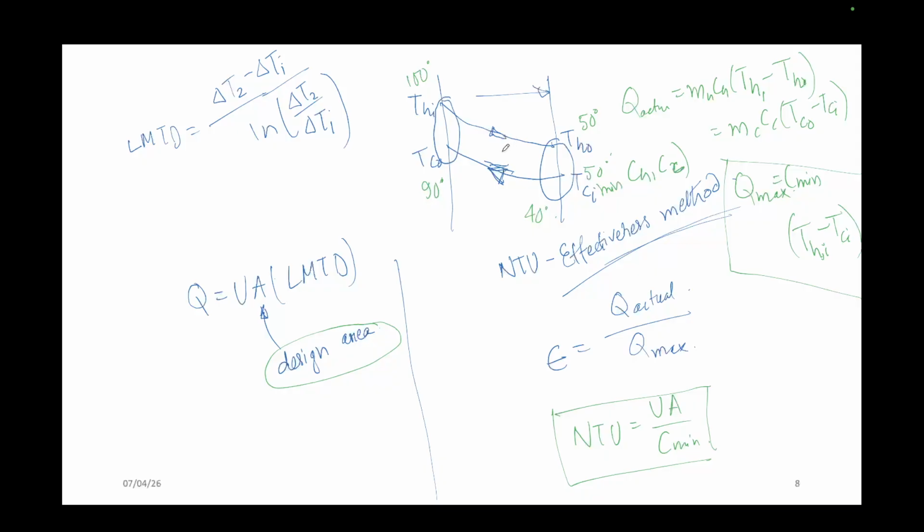that's why the efficiency is better. See, if you are doing a work uniformly, you can do it for a longer period of time. But in the previous case, in the parallel flow, you see the curves converge at a point. That means initially the heat transfer will be more, and after a certain period, the heat transfer will be less. It's like a cricket match.